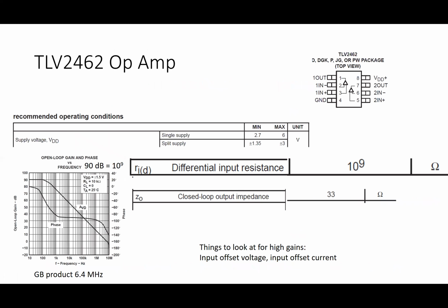Okay, here we are, data sheet time again. I offended you at the beginning of the course by talking about the ATmega microprocessor datasheet, which was truly intimidating. The datasheet for this op-amp is much less intimidating because it's much simpler. Let's take a look at the pinout diagram here. These chips all have a little fiducial mark, usually a little cutaway here or a little circle here or both. And this means when you look down on top of the chip with the pins pointing downwards and you see this little cutout symbol, the pin on the top left is always pin 1.